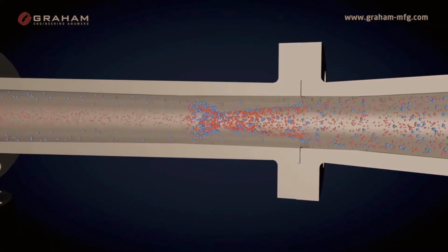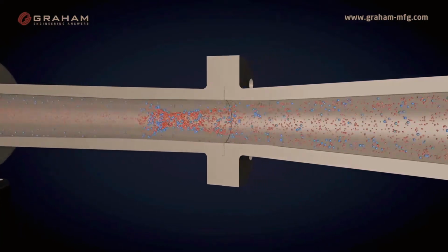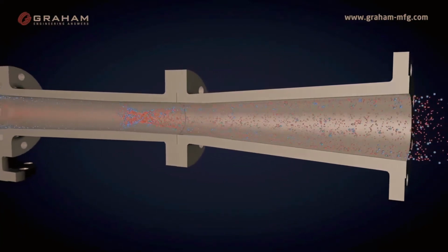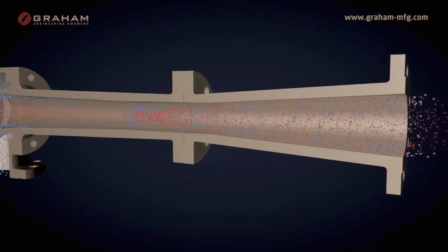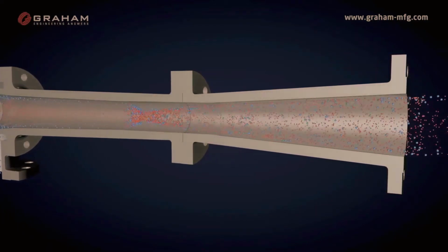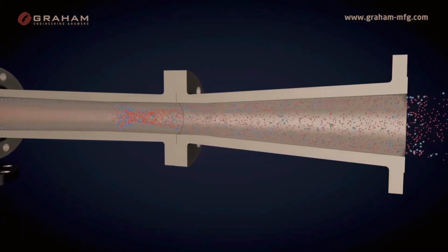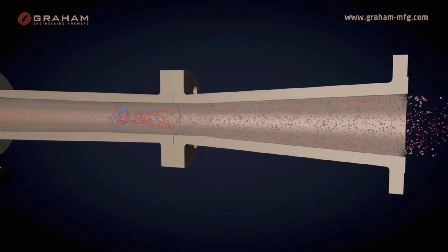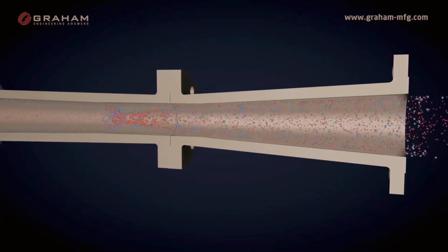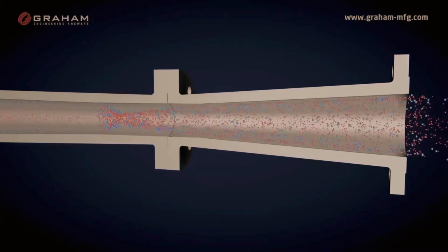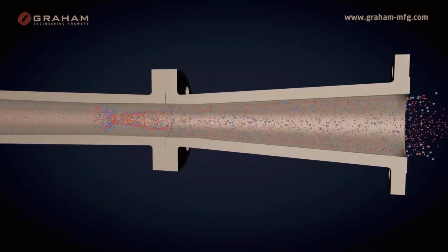The pressure is increased further in the outlet diverging section of the diffuser, where the subsonic mixture is reduced as cross-sectional area increases from the throat diameter to the discharge diameter. Slightly less than half of the total compression achieved in an ejector is obtained in the outlet diffuser section through simple deceleration of the subsonic flow.